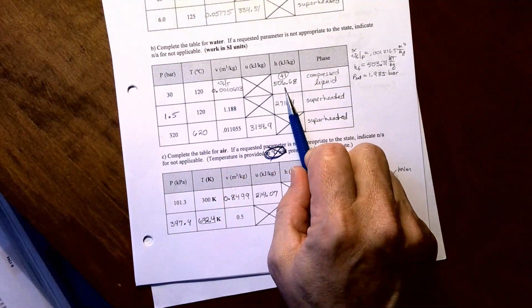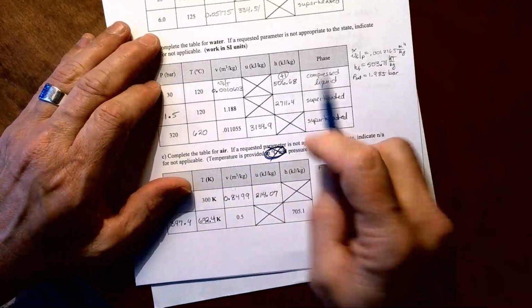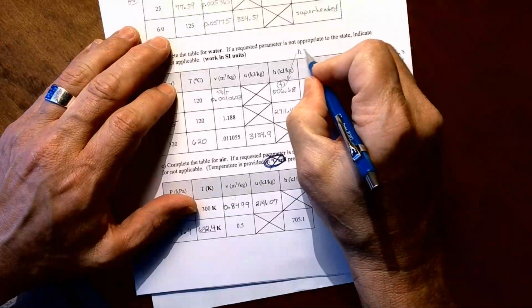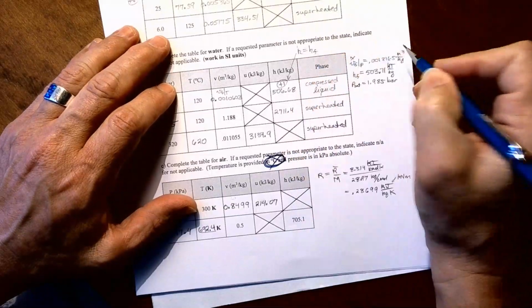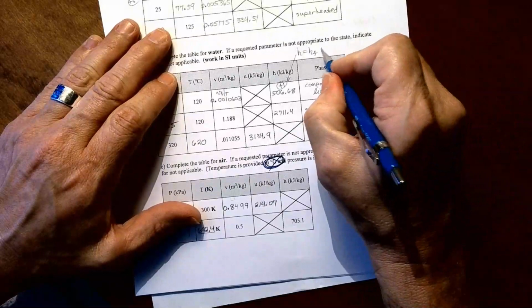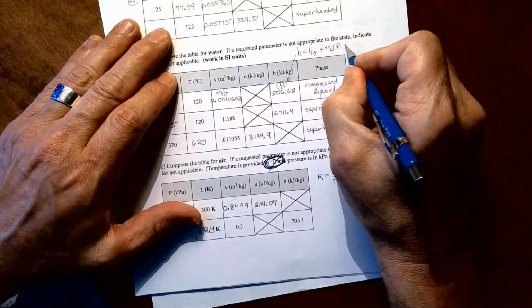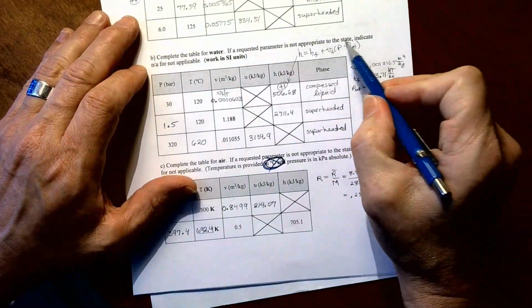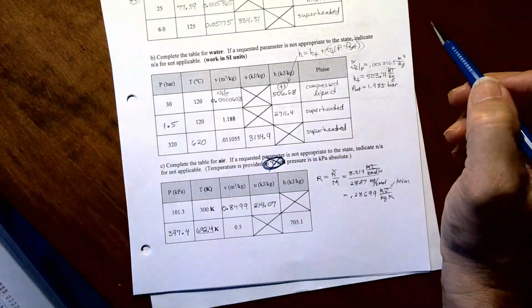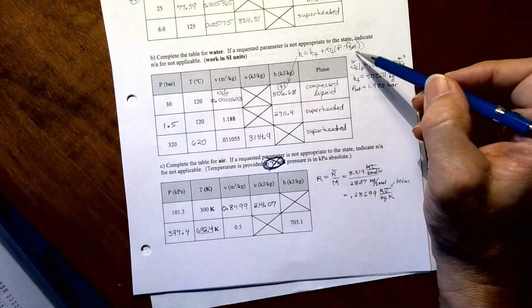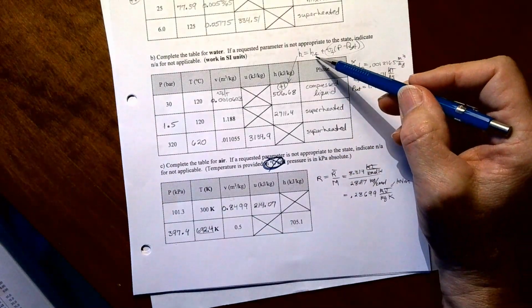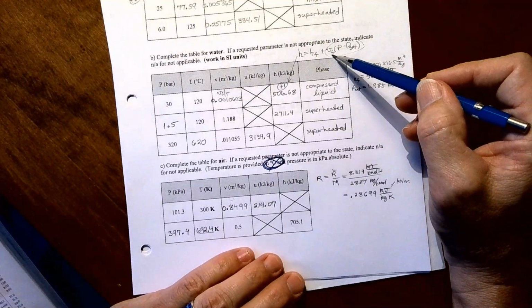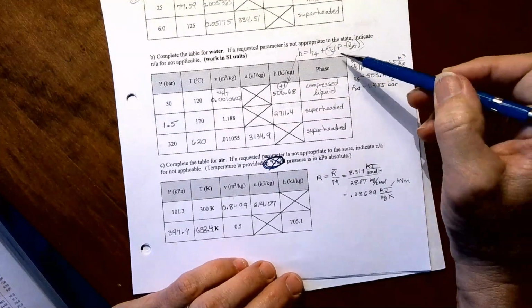And then to find h, that was a little bit more challenging. For that h, remember that calculation of h is equal to h of the saturated liquid plus vf times the pressure minus the saturation pressure. So we have this extra little contribution for an incompressible substance. Okay, so hf, we can get that right off of the charts. vf, we already have. The pressure is 30 bar.